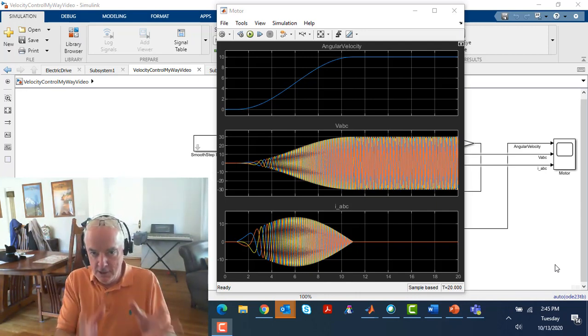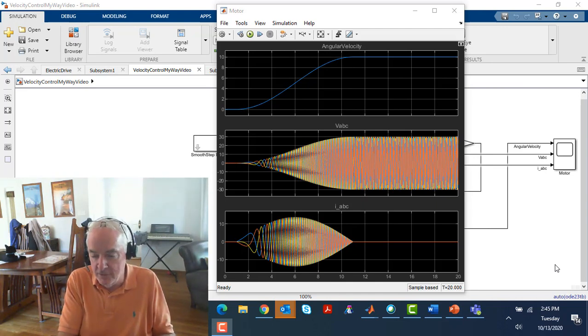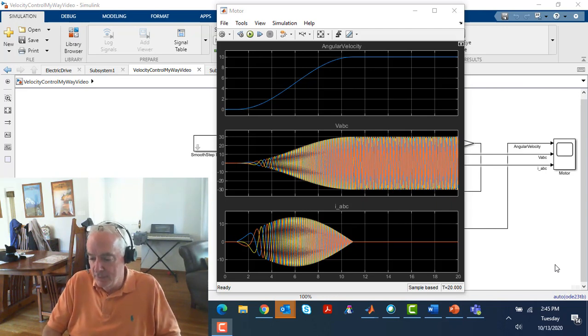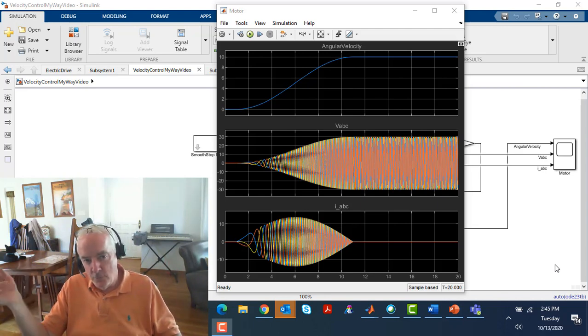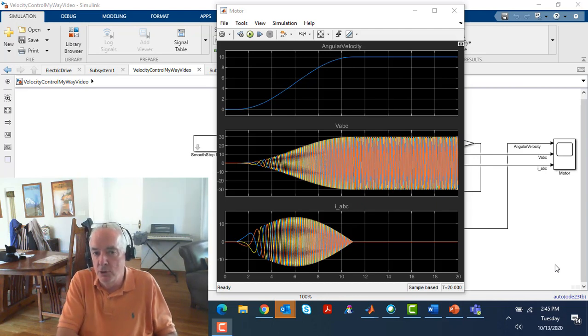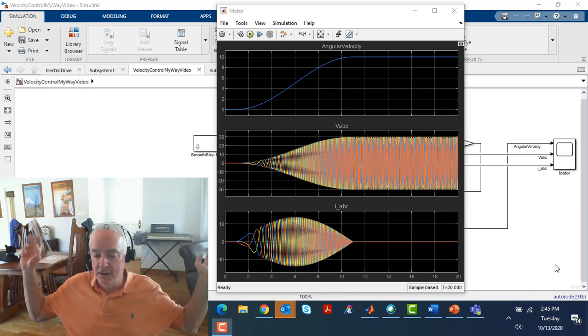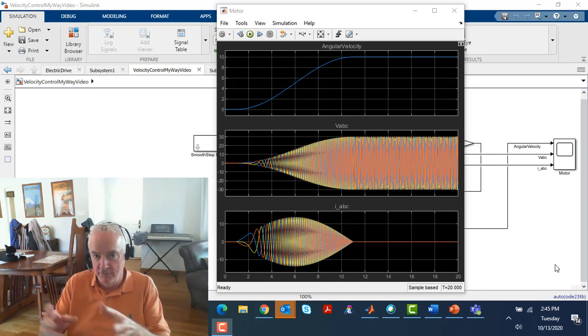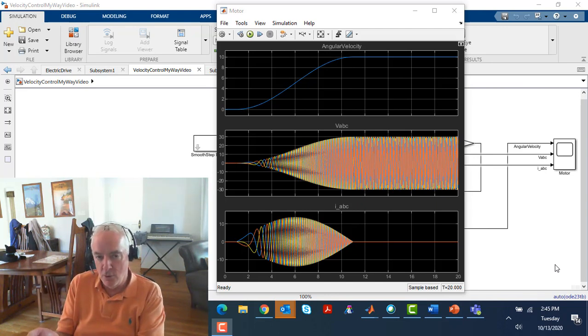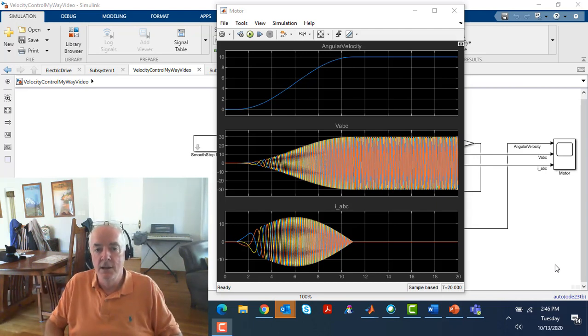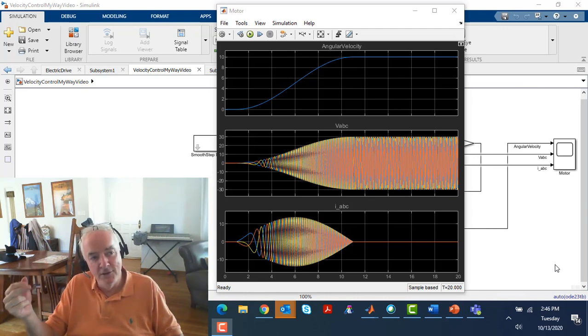We're going to continue our conversation about field-oriented control, but in this video, we're going to focus specifically on this feed-forward piece. Before we jump into the whole electric motor thing, I thought it'd be good to conceptually talk about feed-forward. Feed-forward is about having really good a priori knowledge, you might call it perfect knowledge or information, of the system that you're going to control, very good information of the environment in which it's going to operate, and finally very good information about what this system is going to do.